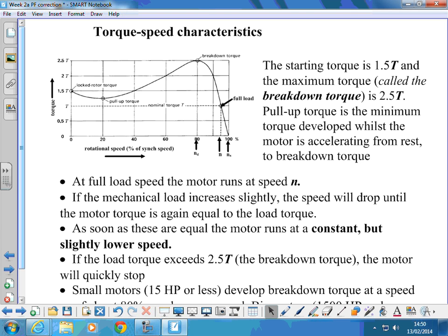Looking at the information I was using to develop this, there's some information about the rotor resistance and how it affects this torque speed curve. They can make the rotor out of different materials, so that changes the rotor impedance or rotor resistance, and therefore changes the torque curve characteristics of the motor.